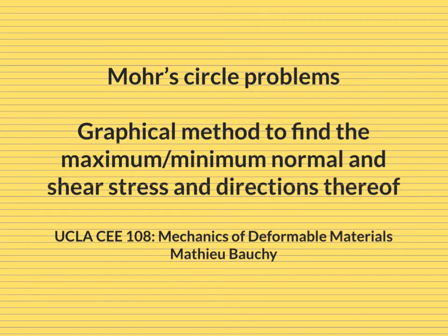As a reminder, brittle material typically breaks under tension. So if you want to see in which direction a brittle material is likely to break, then you would have to find the direction where the normal stress is maximum, where you have a tensile stress that is maximum.